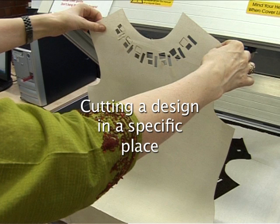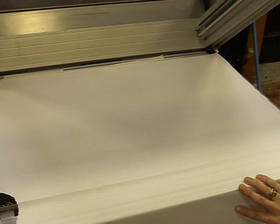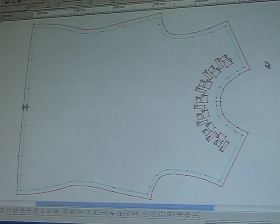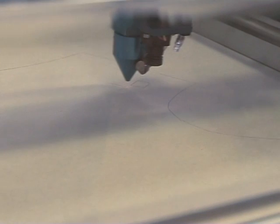Your garment should not be constructed before you use the laser cutter because it won't lie flat, and if you make a mistake you will ruin the whole garment. Place a sheet of paper on the laser bed, lining it up with the horizontal lines of the bed. Tape down the far edge of the paper to the bed. Close the cover gently. Refer to the laser manual and follow the normal procedure for sending your prepared pattern shape with placed cutting design to the laser cutter.